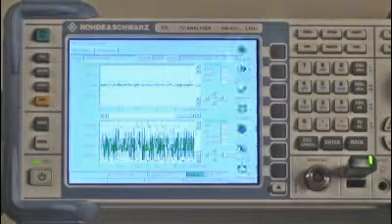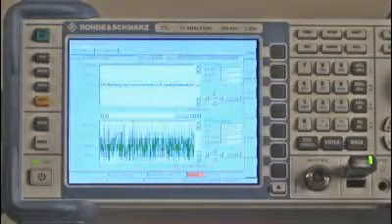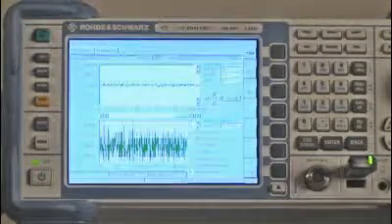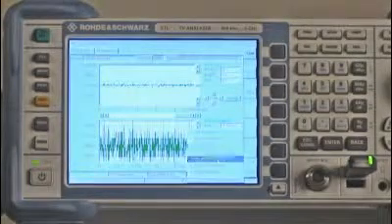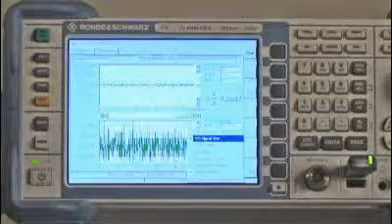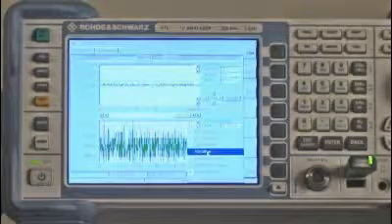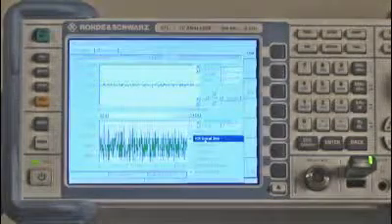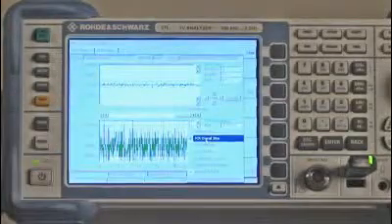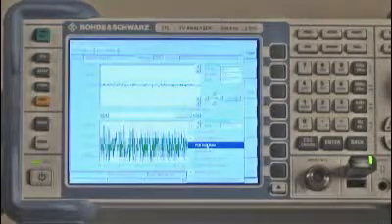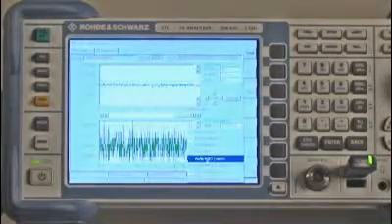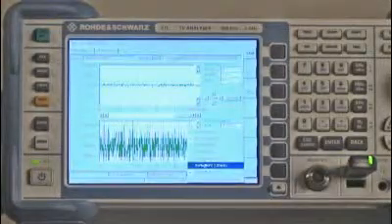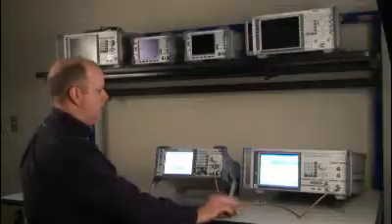At this point, I'm going to stop this and come down to configure and actually show you that we can set up whatever type of PCR measurements that you want to do, either accuracy, overall jitter, which we're doing here, PCR drift rate, and PCR offset. We do have 3 automatic profiles that are already set up depending on what your needs are.